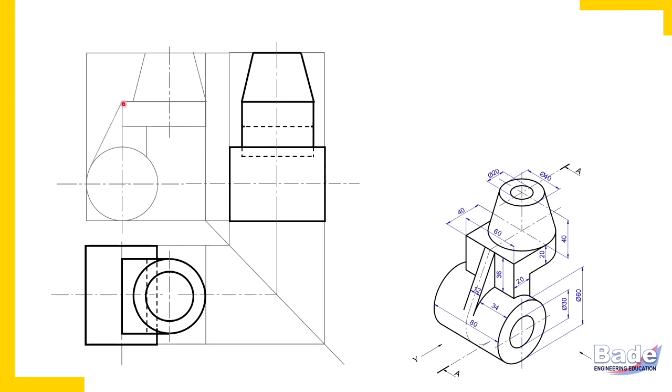Okay, and now we'll draw that rib. Watch here, this is that rib. In the top view, transfer end projectors. Watch here. So this rib is tangent to the curved surface here. Watch, it meets tangentially. So that is why just from this corner, this corner in the front view represents this